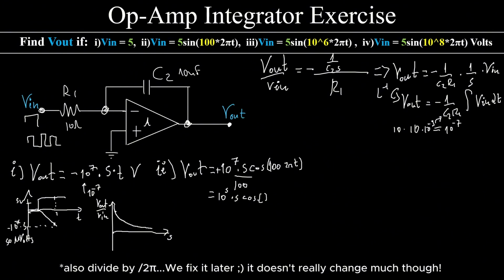That means that when we work at smaller frequencies, we expect to get higher amplitudes at the outputs, but when we work at higher frequencies, we expect a smaller value. This will work as a very good low-pass filter, but we must be very careful again with the DC signals over here. So this circuit as is